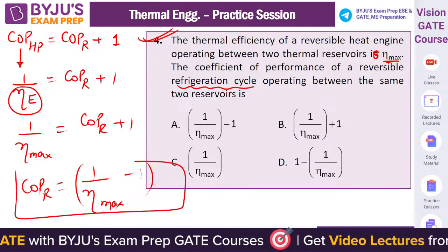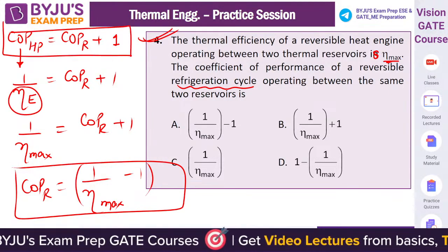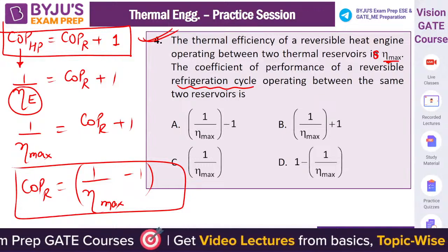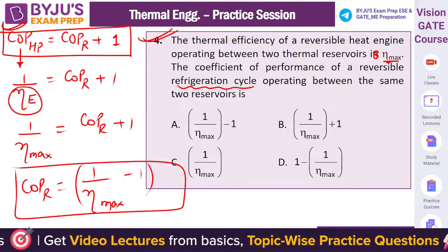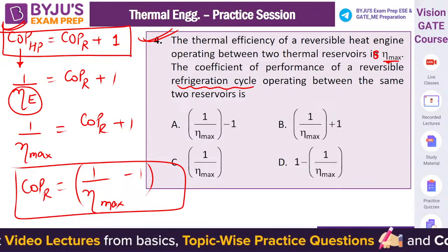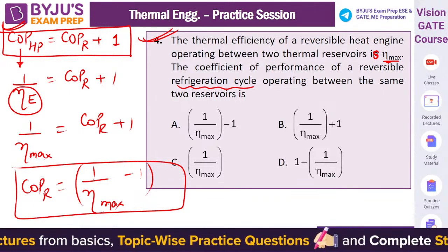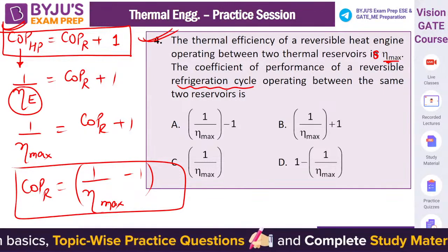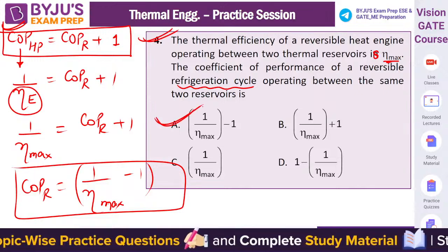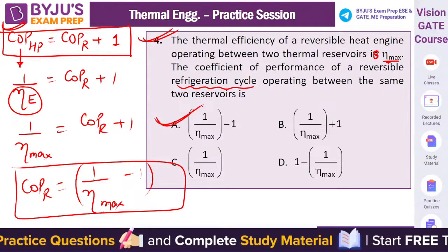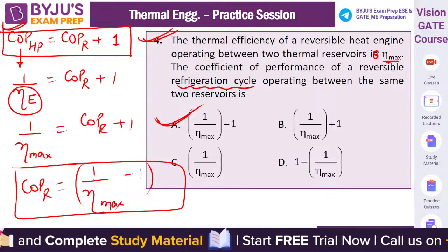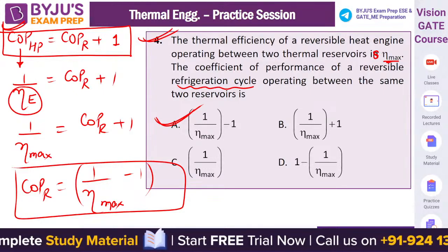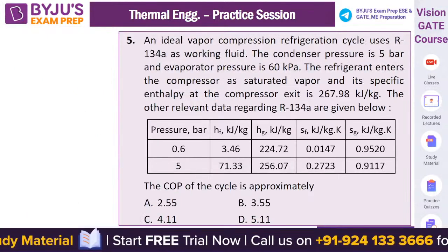Very simple. These are the two expressions you need to understand. One is COP of a heat pump is 1 plus COP for a refrigerator, and COP of a heat pump is the reciprocal of thermal efficiency of the engine working between the same reservoirs. A will be the correct answer. Yes, well done, Kiran, TPM, Maniket, A will be the right answer. Let us move to question number 5.